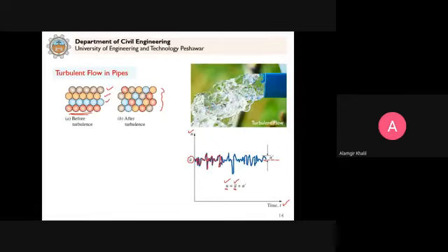So at any instant, the velocity will be equal to that time average, u bar, plus u dash. This is the fluctuating component. And this fluctuating component can be plus, can be minus. You can see above the line, below the line. So this is how velocity calculations in turbulent flow become complicated. And this is only considering the velocity in x direction.